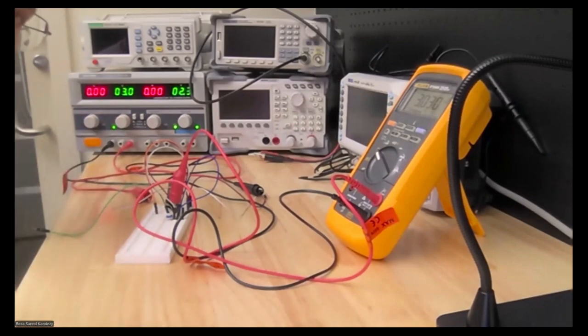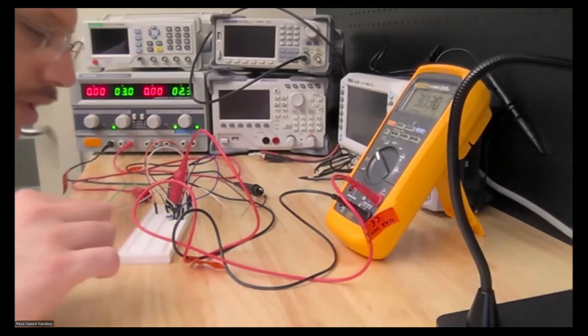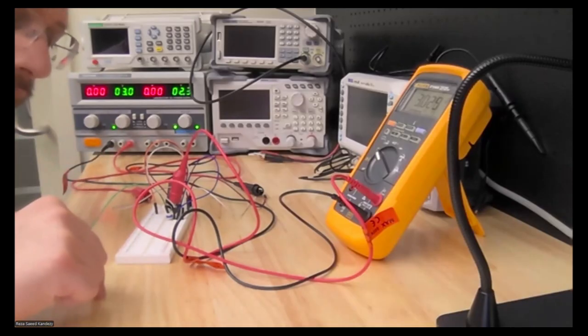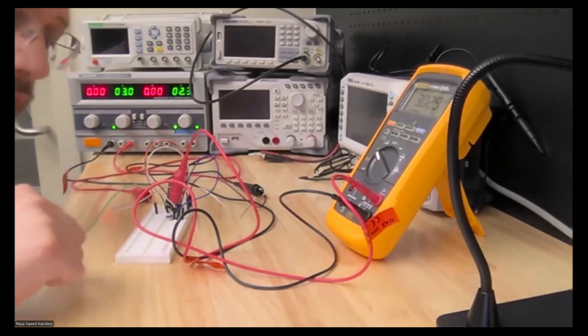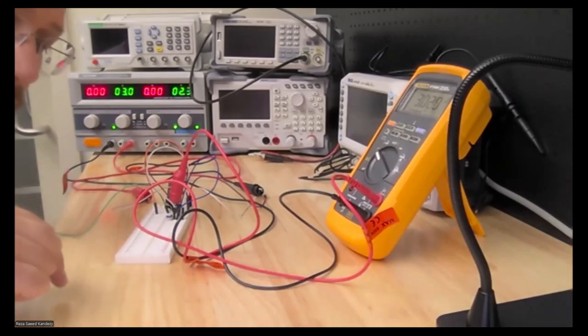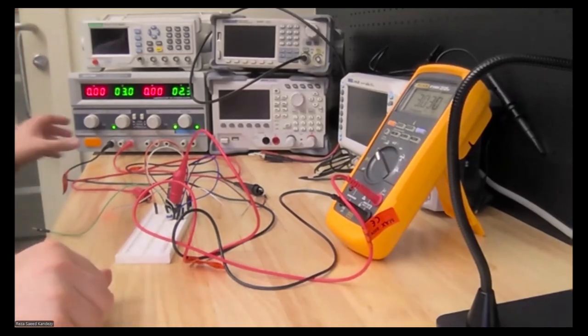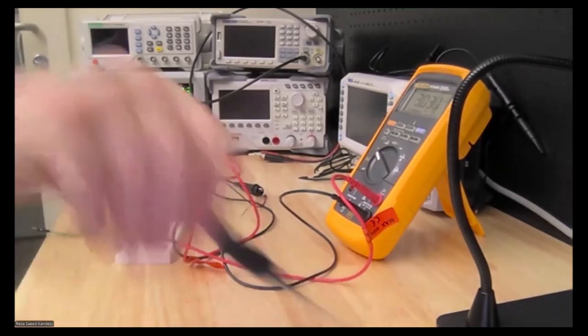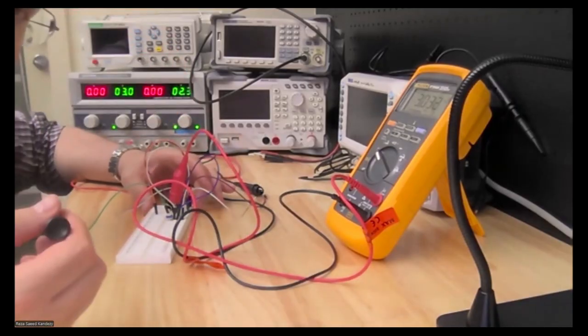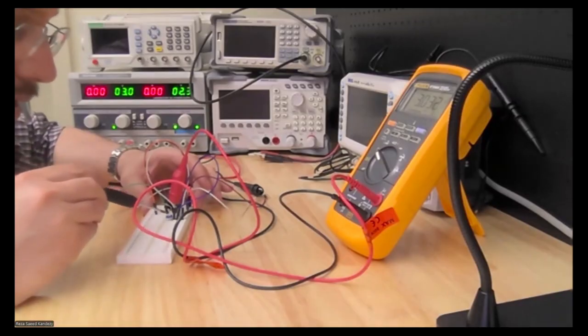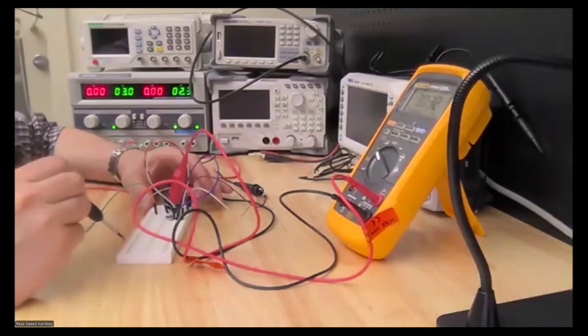I don't remember. But check the video. Go back and check the video. And for that 4 milliamp, on that curve, it happened on the VCE 3 volt. Now, we are gonna change the voltage. How we gonna change the voltage? By changing the potentiometer that we use as a resistor in series with the collector.